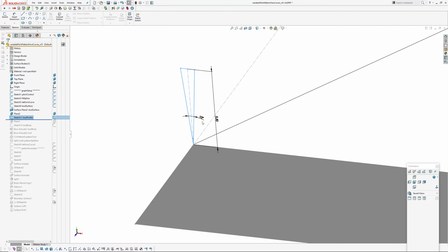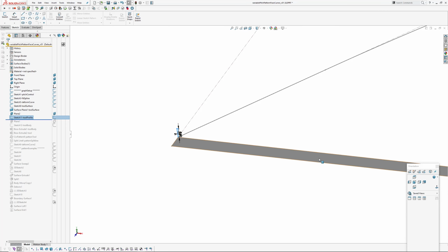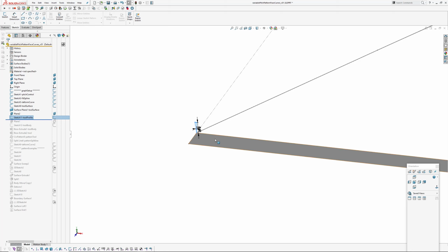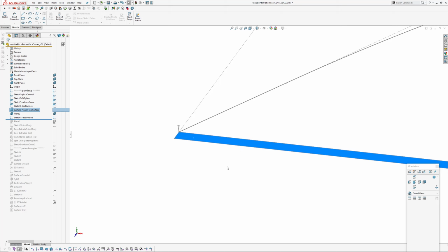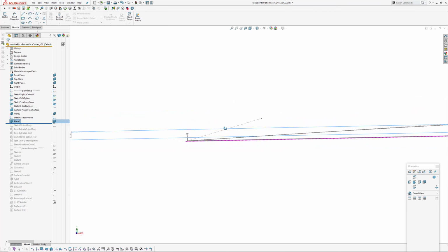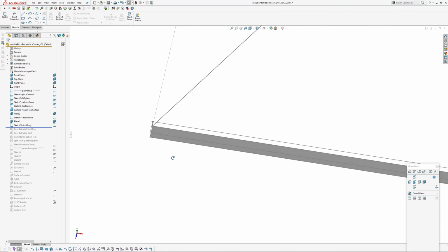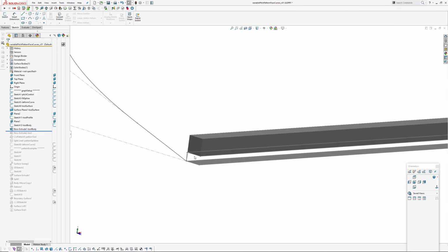That angle could be anything. When I make my pattern across here, I need to make it into a single solid, so I can then use that single solid with lots of these wedges on it to split. You insert split lines across this tool surface in one go. It will all become obvious in a sec. The plane's just the top of that wedge, and I've made a tool body, which is again just a rectangle, so converted entities of the tool surface, and then made a boss extrude. It doesn't matter about the height.